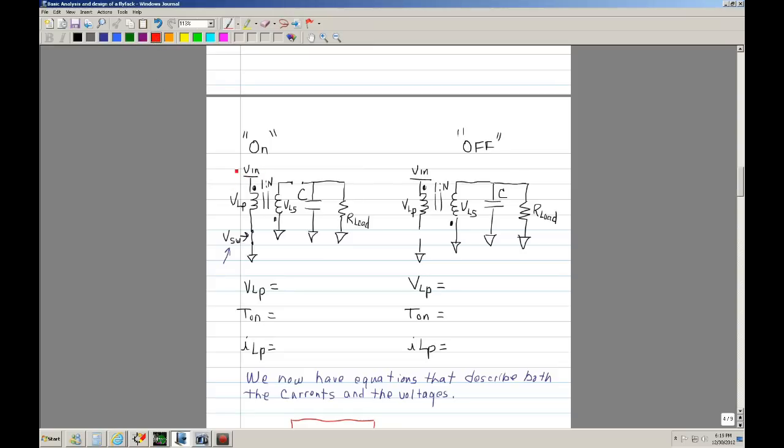Well, since this is positive voltage, there's a positive voltage on the plus sign on the primary, and you're going to have a positive on the secondary as well. Since the non-dotted side of the primary is connected to the ground, you have a negative, so that means you're going to have a negative on the secondary undotted side.